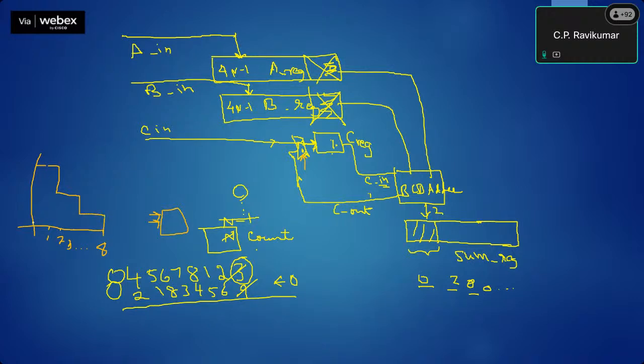But I can't say the same thing about the delay of the BCD adder; it may not scale linearly in any way. That will depend on what gates are used inside, what is the load on the interconnect. So it is not very clear. It's not obvious that one is better than the other. So if somebody wants to look at which one will be better, they have to go into actual analysis of the design.